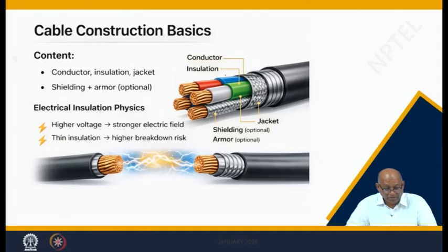So, if you continue to other 3 phase cables, for example, here is a cable where many phases are there, 3 phase, possibly 4 phases, the fourth wire can be neutral. Here you see every cable is insulated from the other cable, but these are generally low voltage cables. High voltage cables cannot have 3 phases like this. These are medium voltage, not like 440 volt, it can be a few kV, 3.3 kV, etc. So, these are all the 3 phases together, and the fourth wire is for neutral, it may be, all right.